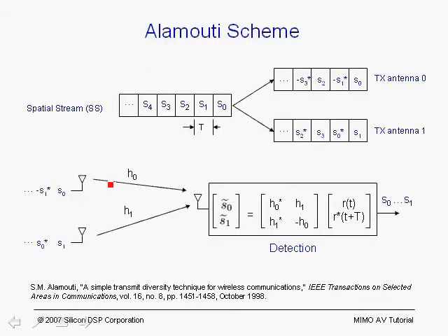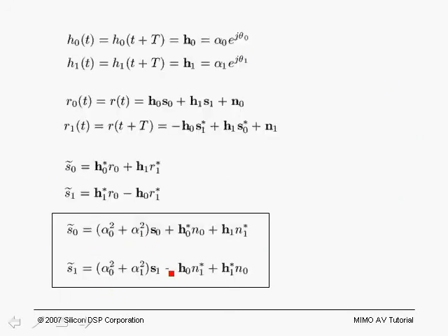Again, looking at the two separate paths and considering the fact that the transmit antennas will normally be spaced half a wavelength apart, as we've shown earlier, there's a good chance that if one path exhibits a deep fade, the other path is at a peak or vice versa, or somewhere in between, and here you can see how we get the diversity gain.